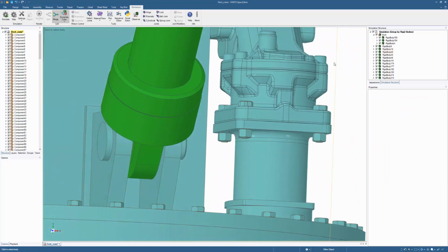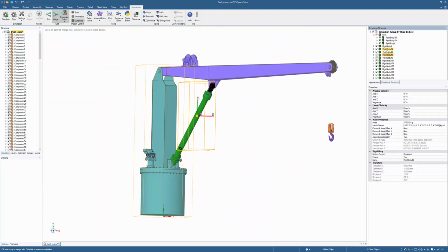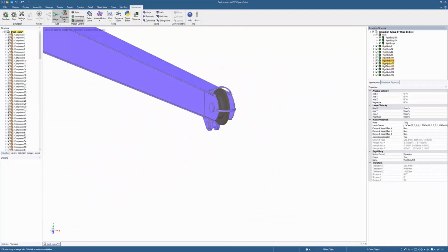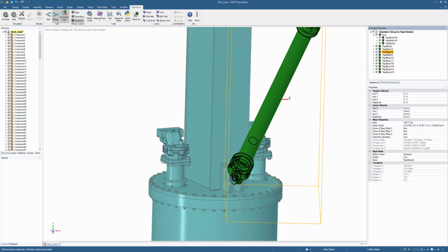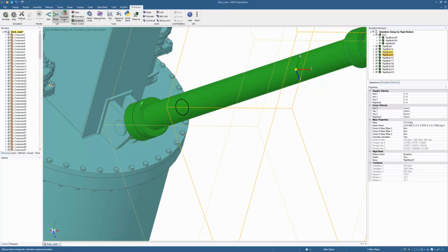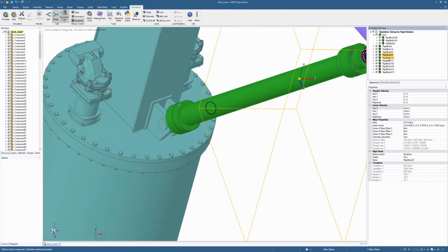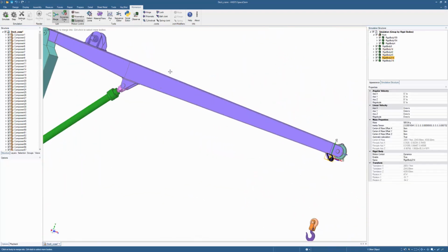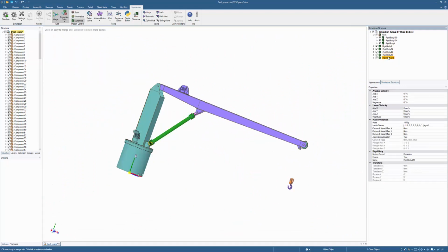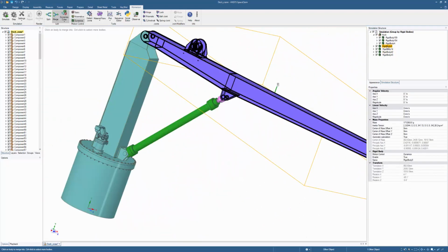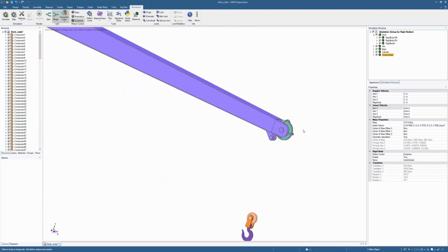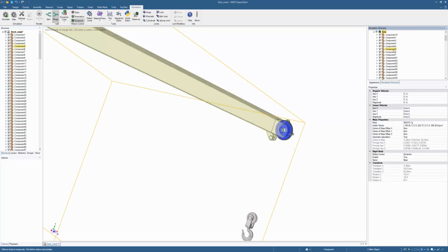It's also a good idea to go through the list of bodies so that you can identify if there are objects inside which are hidden by other objects, because they can cause problems. If they belong to a separate body, then you get contact and they will cause instability in the simulation, or it could jam the simulation. So it's important to get all the rigid bodies correctly structured.